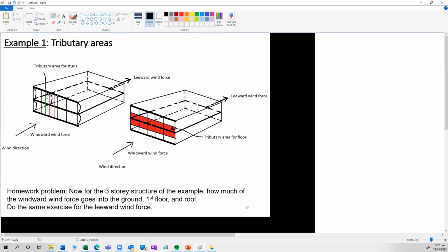So the tributary area is 1/2, just like, imagine these are beams, but you're looking at them vertically. The tributary area is halfway the distance between each stud. So for this stud, from the second floor, that's a tributary area for the entire stud. This stud on the first floor will look like this. It will deflect like this, and this is the area loaded by the pressure.